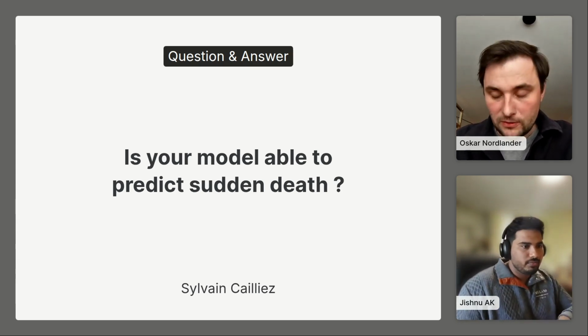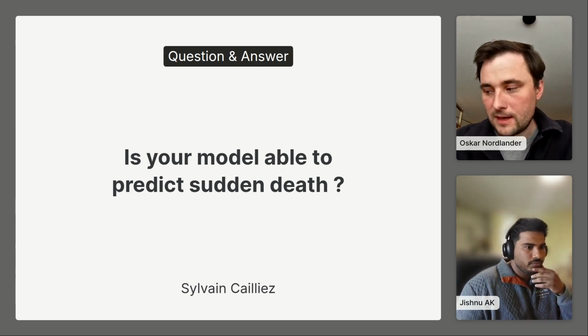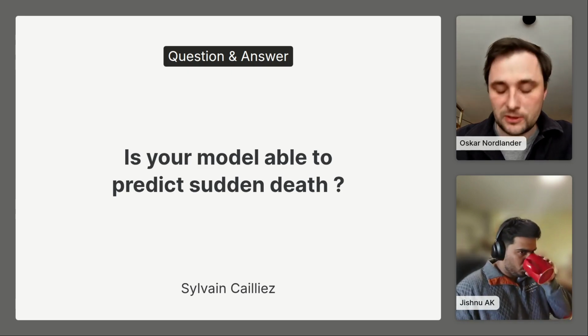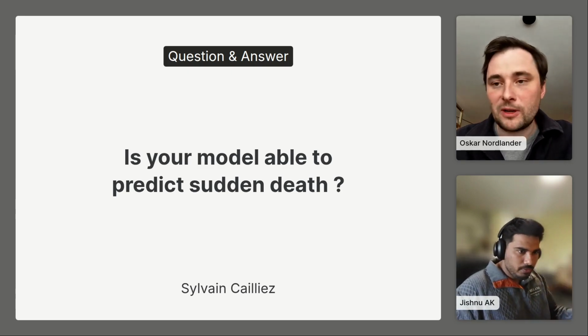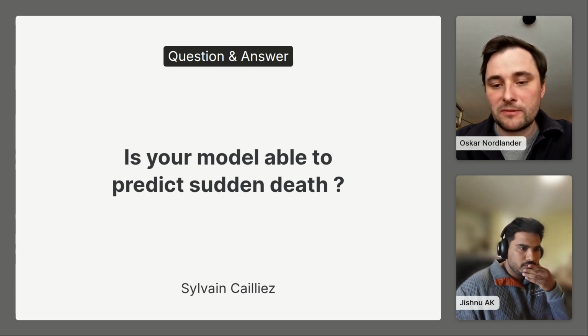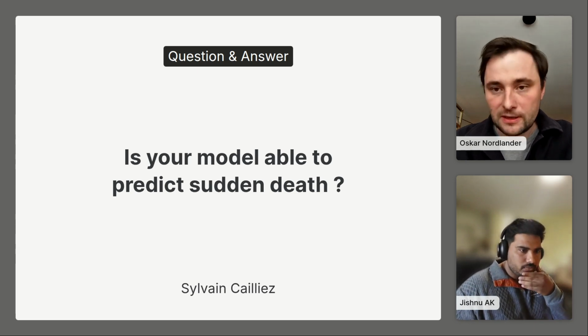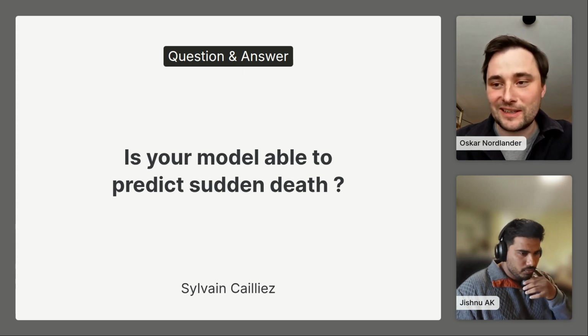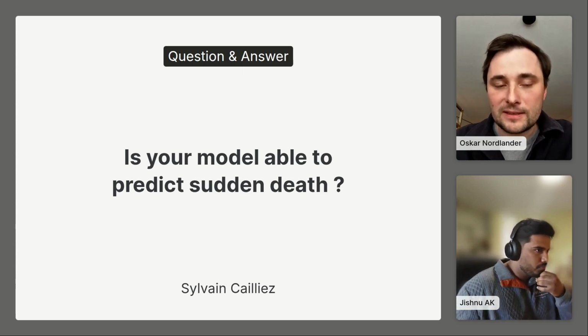Yeah, and to add on this, with all software and models aside, I would like to emphasize that testing is good. This is one of the reasons why testing is good, to actually have some confidence, especially on sudden death or knee point. So in terms of validation and testing campaign, it's a question of which test should be run until the sudden death or the knee point; that is the key thing here.